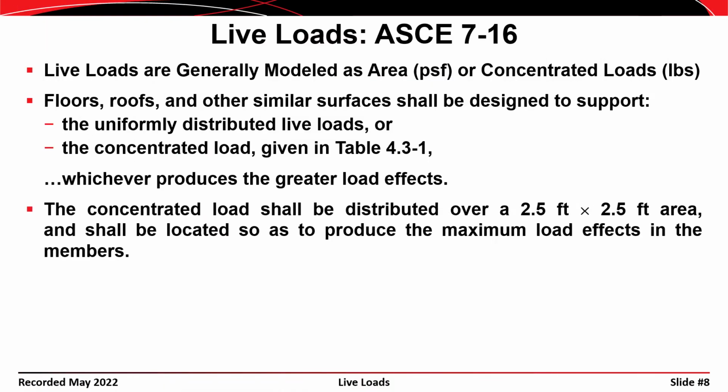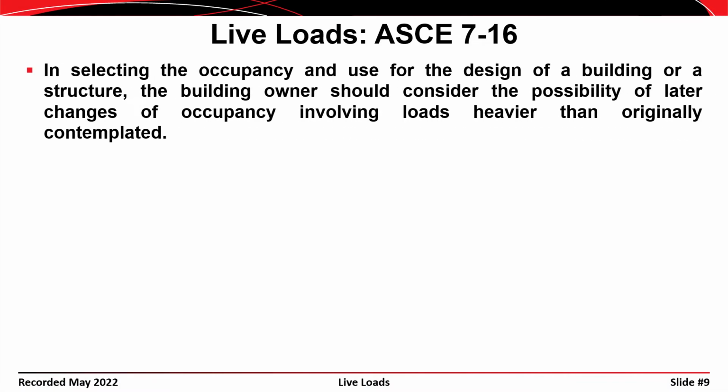Okay, concentrated loads, when you design for them, shall be distributed over an area that's 2.5 feet square and shall be located so as to produce the maximum load effect in the member under consideration. In selecting the occupancy or use for a building, you should give consideration to the possibility that changes in the structure might lead to heavier loads than originally contemplated. We mentioned that just a couple of slides ago.